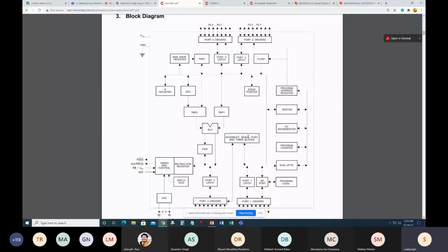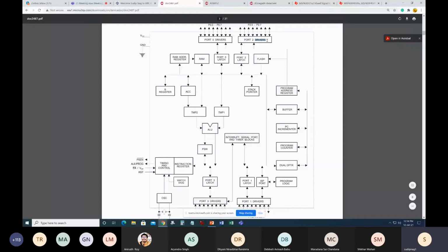Another thing I missed out is this buffer. This buffer is again similar to these kinds of drivers, and it is a bidirectional kind of NOT gate arrangement. That means there are 2 NOT gates looking outside, and 2 NOT gates looking left to right, and 2 other NOT gates looking right to left for each of the pins. So here this is an 8-pin buffer. See, the point is these port pins are 1 pin outside, but whenever you see this kind of line over here inside, obviously each line is actually part of the bus over here.